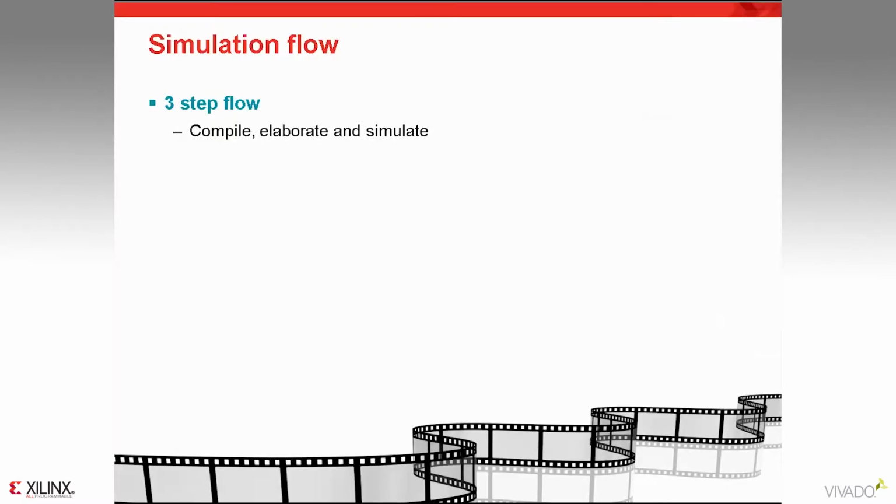The simulation flow uses a three-step process: compile, elaborate, and simulate. ncvhdl or ncvlog for compile, ncelab for elaborate, and ncsim for simulate. Vivado creates separate scripts for each step so that users can take the compile and/or elaborate script to their own custom environment.